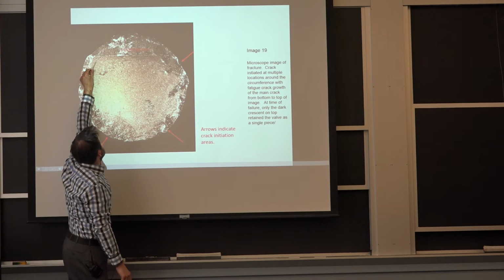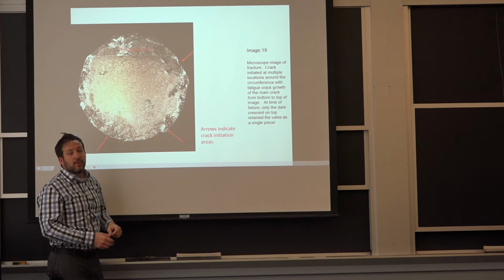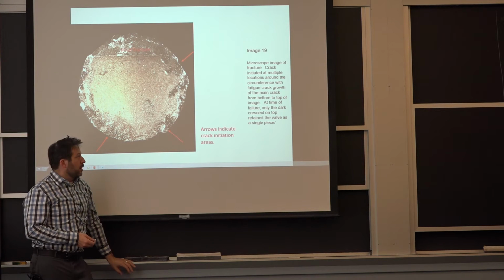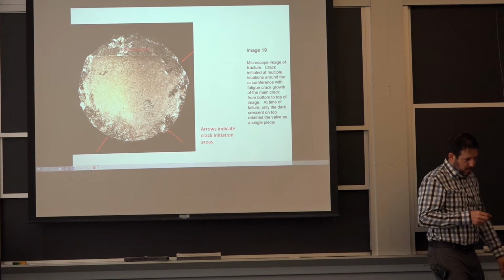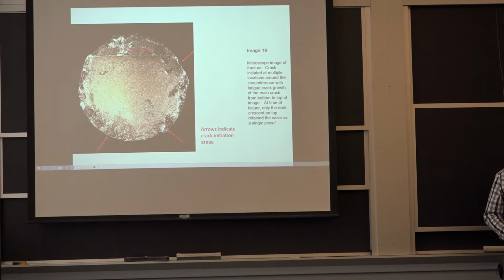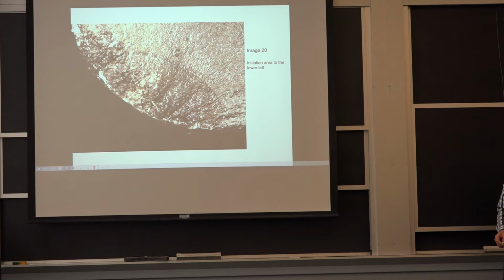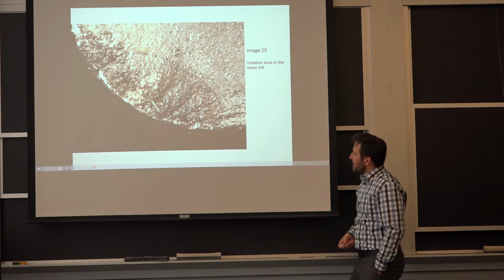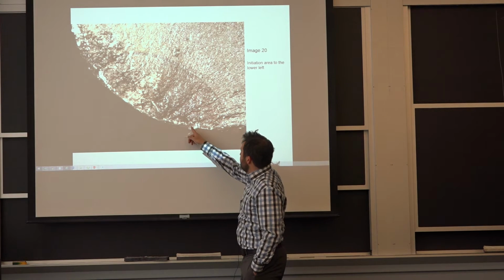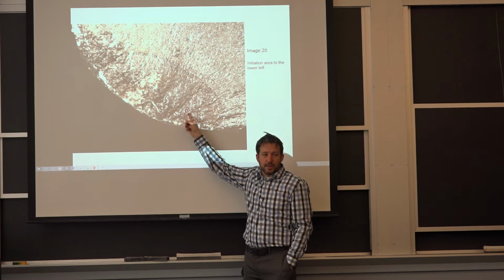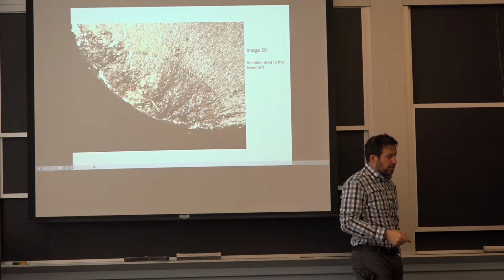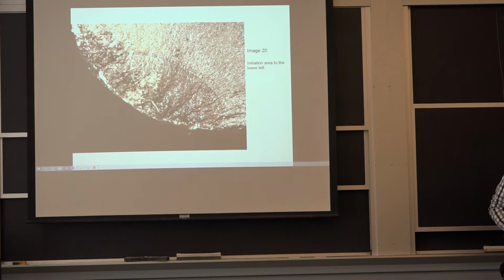Oh, here we do see this is the overload line where we reached our fracture toughness value. So a lot of life spent, again, in growing a crack. And the question which you guys brought earlier, okay, so why did the crack start and how could I prevent it? If we want to know that, we have to look close to the initiation site. In this case, it's hard to know something. Maybe here there was a little bit of missing material. That's what it looks like, but it's not super conclusive, at least on first view.